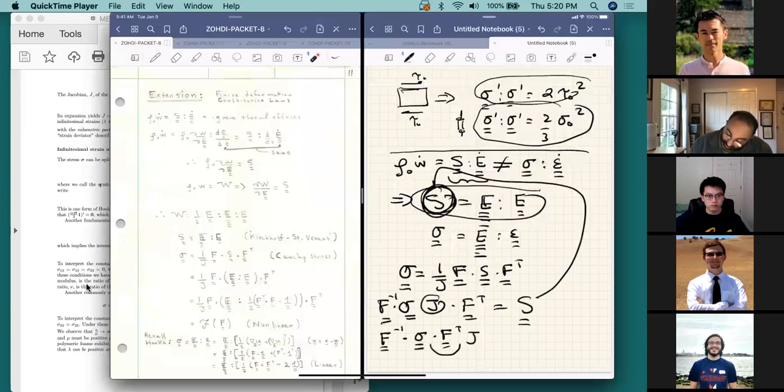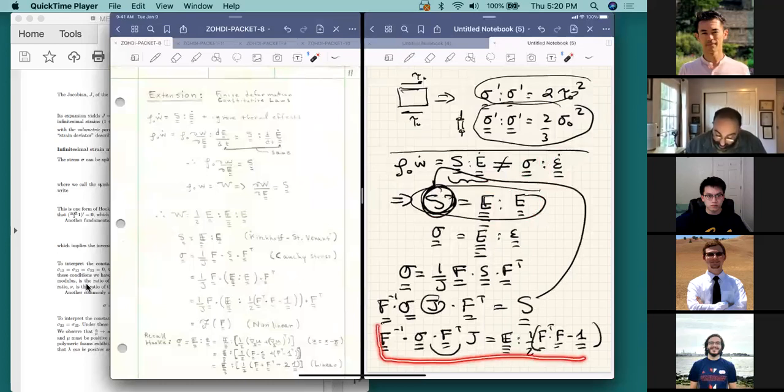It looks like that. And then this is equal to, in this case, E, the elasticity tensor, multiplied times 1/2 F transpose dotted with F minus 1, because that's, of course, what the Green-Lagrange strain is. So this law is anything but linear. When you start to look at it, it has a very weird relationship between sigma and F. While the first law of thermodynamics dictates that's what it has to look like, it isn't an option for us.